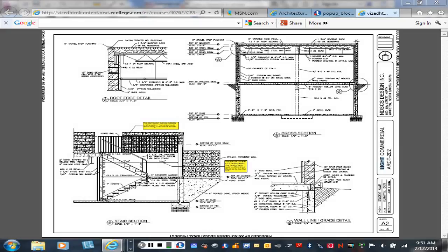But you'll notice that we talked yesterday about our columns being somewhat in the wall, in the masonry, because it's 8 inches in from the corners of the building, so we have to be furred around. Well, when you get up to the roof level, there's a steel beam running across that's also incorporated into that wall, right? So we're going to come up with our 8-inch masonry to a certain point, and then we're going to have to go with a smaller block to create the parapet part of the wall so that the steel beam doesn't interfere with the wall.